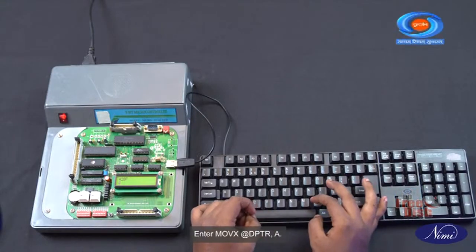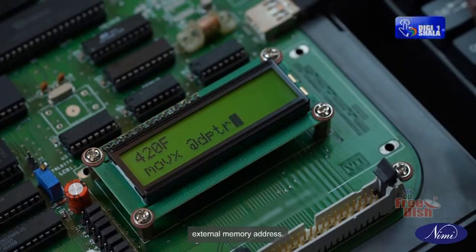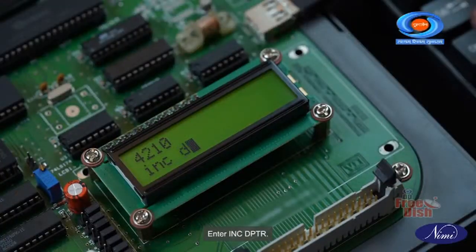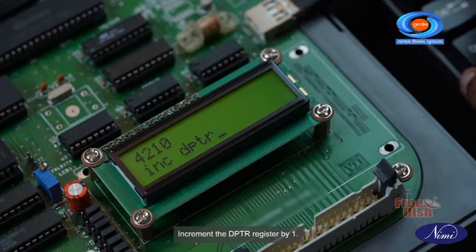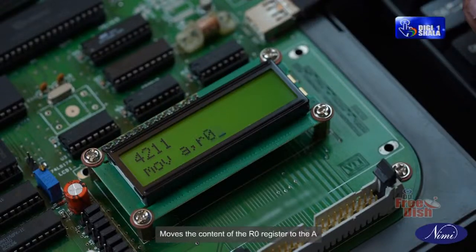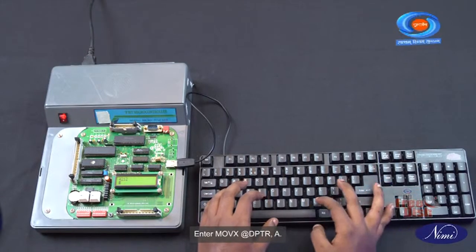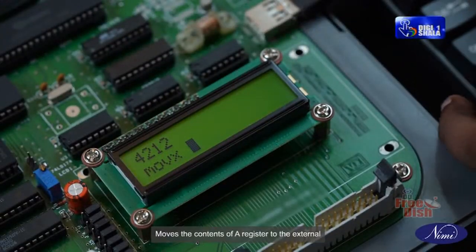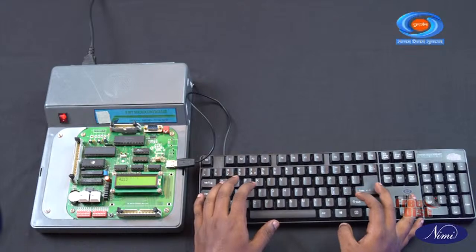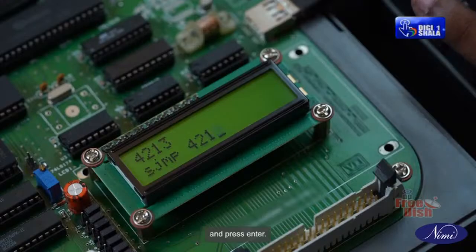Enter MOVX @DPTR, A. Moves the content of the A register to the external memory address. Enter INC DPTR. Increment the DPTR register by 1. Enter MOV A, R0. Moves the content of the R0 register to the A register. Enter MOVX @DPTR, A. Moves the contents of the A register to the external memory address. Enter SJMP, type the same address displayed on the screen and press enter.